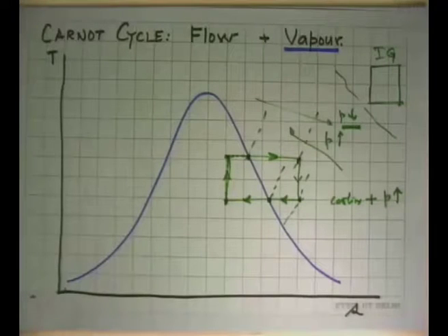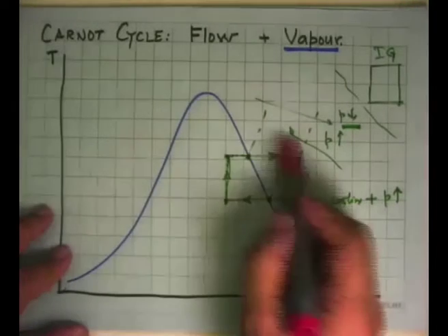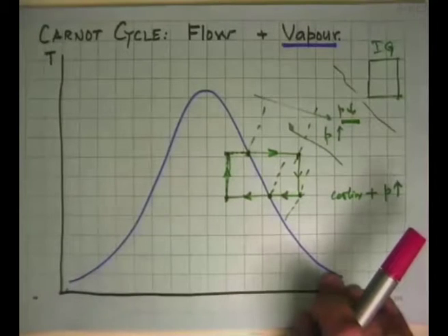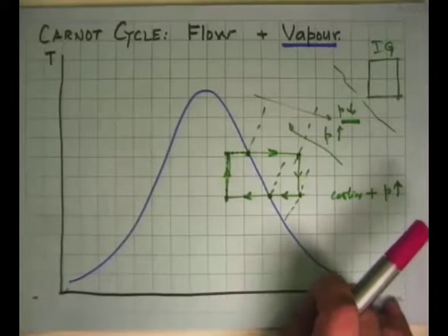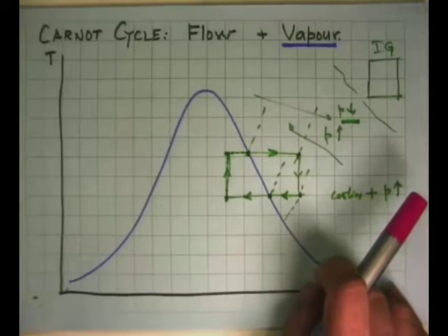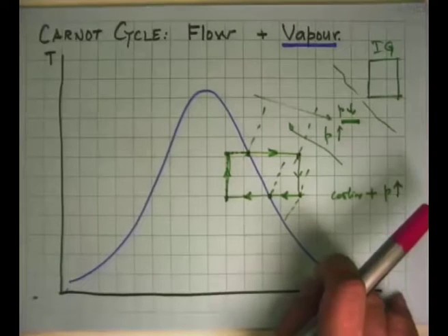So let's see now what are the other options we have and what are the closest that we can get. First, let's try to avoid heat transfer processes where there is a pressure change. So I will not make a device in which I will have heat transfer with pressure change. I will make a device where heat transfer takes place at constant pressure, constant temperature.